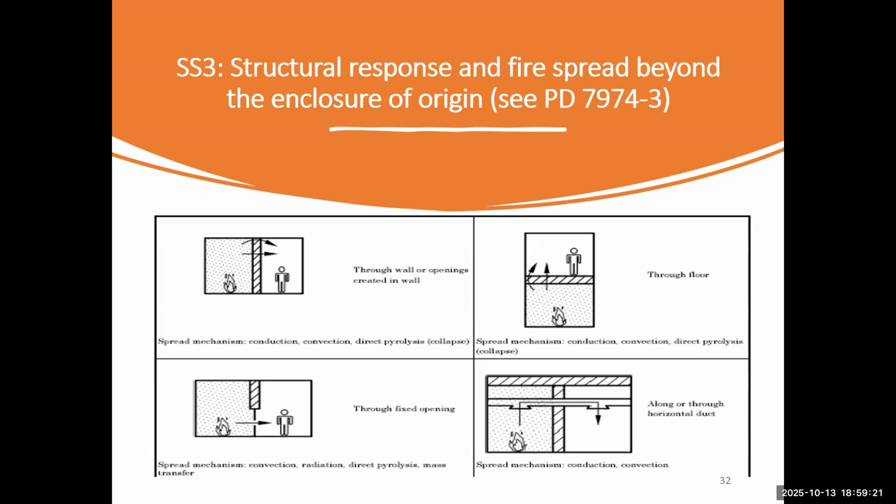From this example, we know that the methodology for subsystem 3 firstly involves defining the fire enclosure. The analysis then evaluates the element's thermal and mechanical performance under this environment. After comparing with the critical failure criteria, we can predict the failure time and the duration before the fire spreads beyond the compartment.